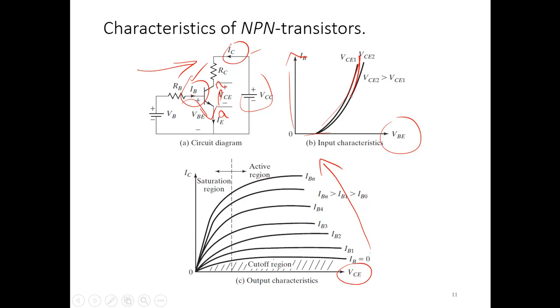Okay. And then once you have that base current, you adjust the base current. If you adjust the base current, the collector current is adjusted. That's the active region where you operate the transistor as an amplifier, like in your electronic circuit. But here we are working with a switch. Then we should apply a base current so that it operates in the saturation region. That issue comes: how much is saturation? You give it too much or too little. That's the issue to consider.